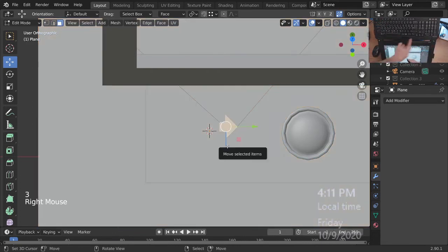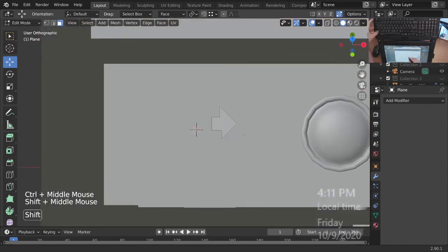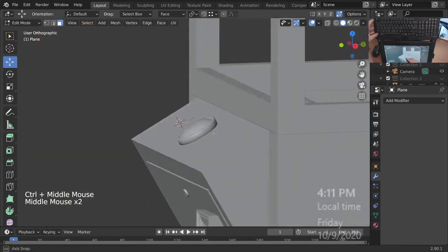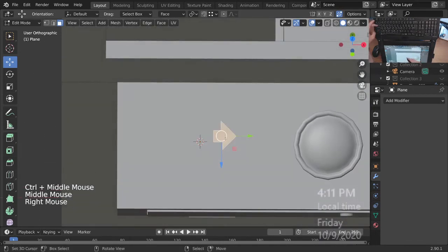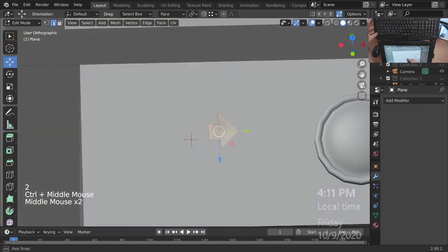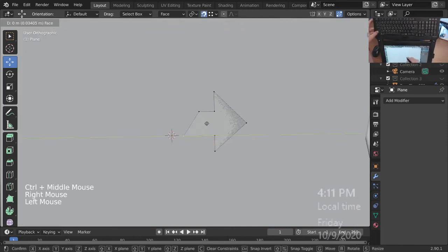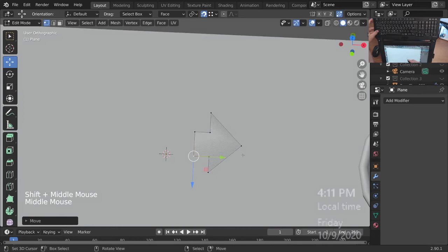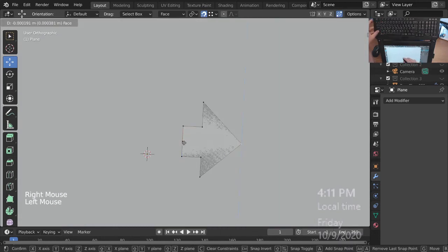Select that face and then Control and invert X faces. So that should be one of the arrows there. It's off, obviously, but all I'm going to do is go into the vertices and line them up. Take that one, line it up.